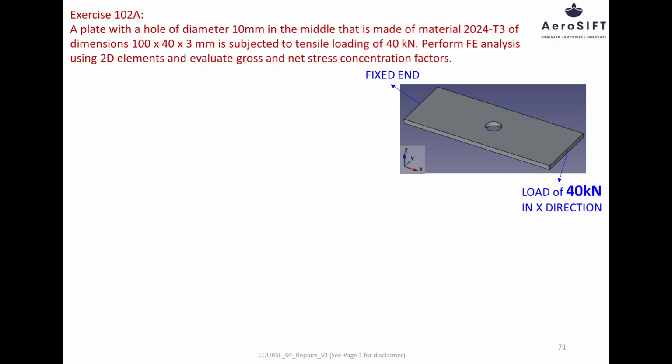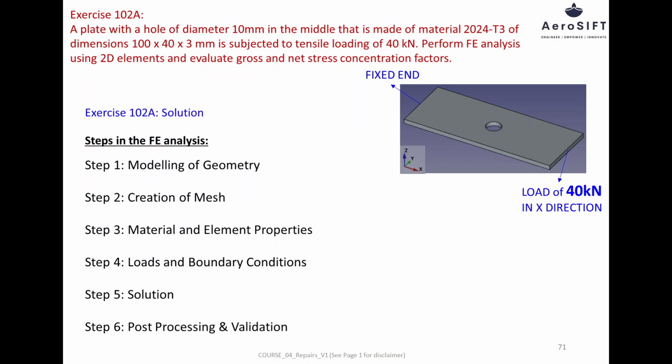The aim is to carry out a 2D finite element analysis to evaluate both the gross and net stress concentration factors caused by the presence of the 10 millimeters diameter hole. The solution follows the standard FE analysis process, from geometry modeling to post-processing.